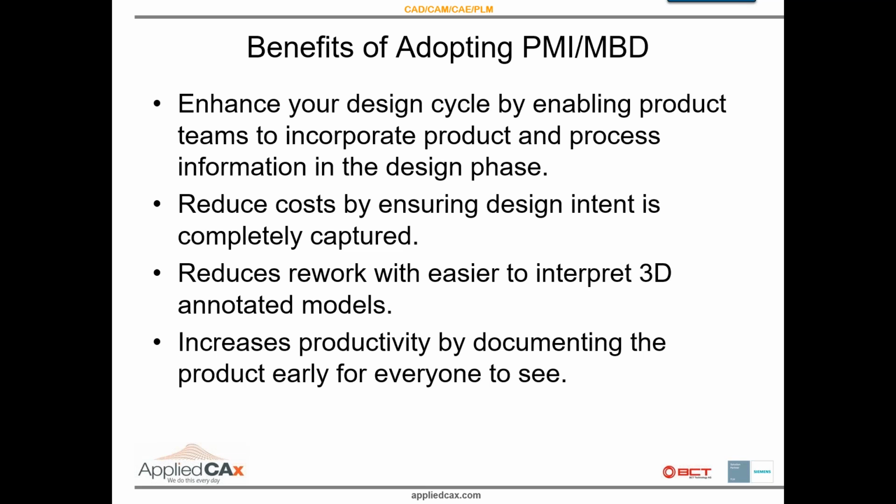You can more accurately capture the design intent, thereby reducing the amount of rework you end up with. A 3D annotated model, as we'll see, makes it a little bit easier to identify exactly what the dimensions are intended to convey. And lastly, it increases productivity by allowing everyone to see the product early and where it's going.